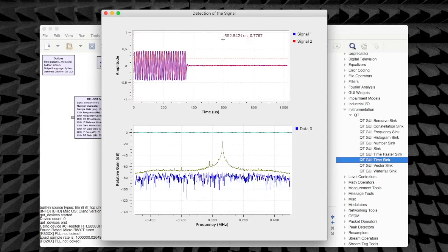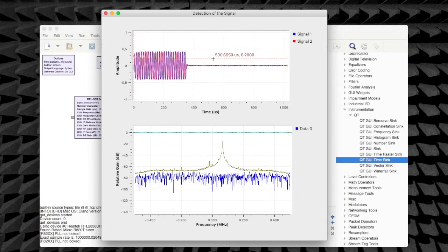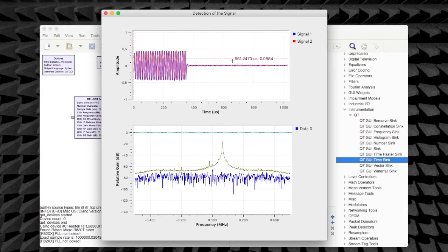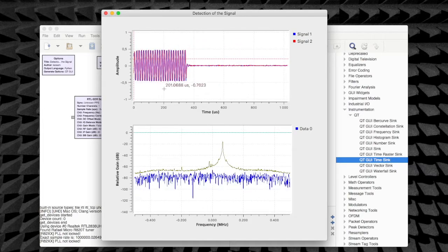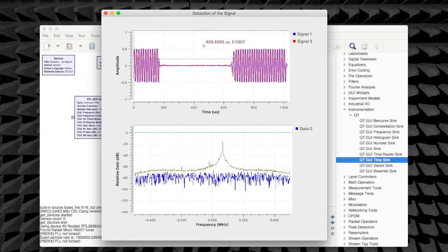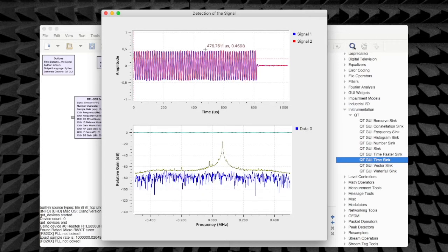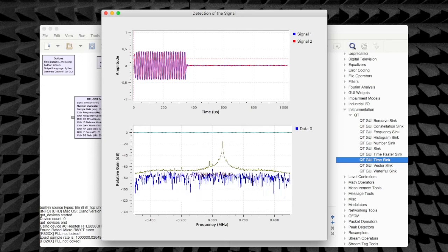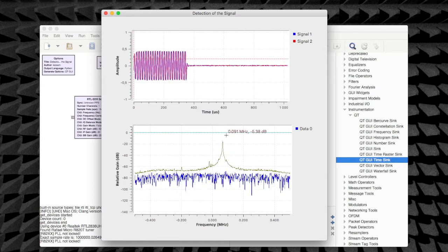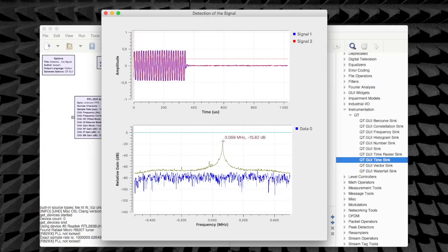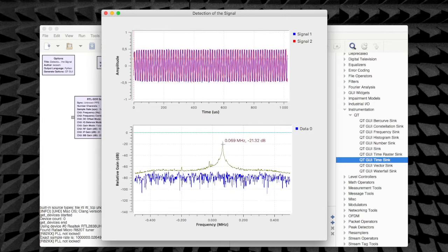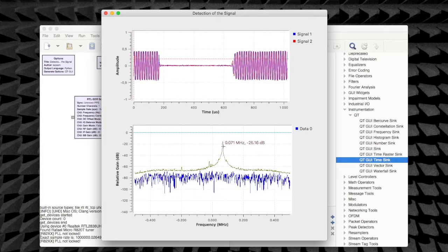We see that the signal is actually constituted with a sine wave here, which contains some spacing of pure noise. This gives me a hint that we might be using something that looks like an amplitude shift keying. This signal can be seen here also on the frequency domain. So if we want to answer the question, what is the bandwidth of the signal, then we can just take the top part here, go 3 dB down, and then look at the width of this signal right here.